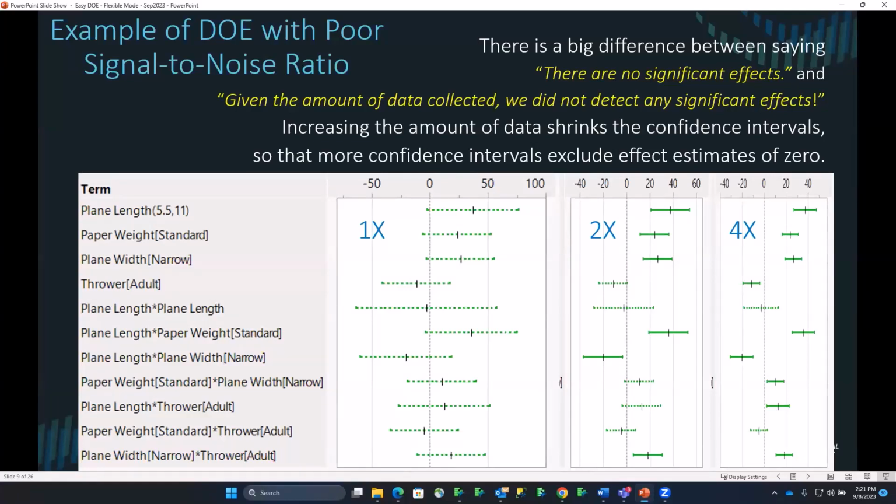data that I take. One of the reasons that design of experiments sometimes fails is that people have inadequately understood the signal to noise in their process. Sometimes people are too timid with the variables. If you don't turn a knob very much, you don't make a very big effect. Sometimes people aren't aware of how much variability there is in a process, and you'll know this from different industries.